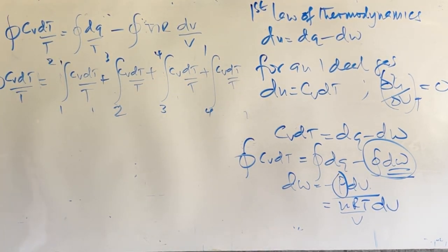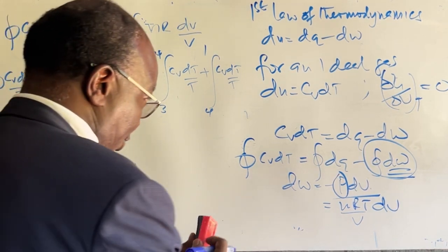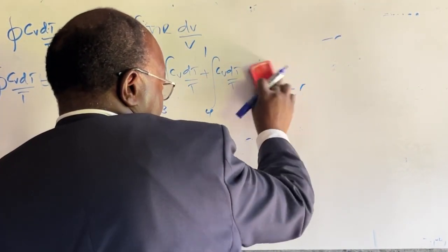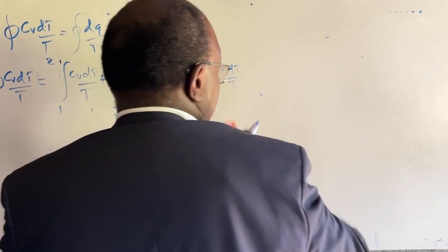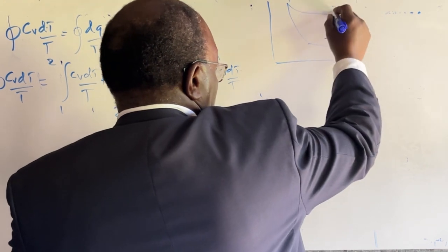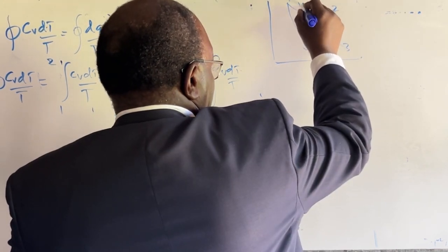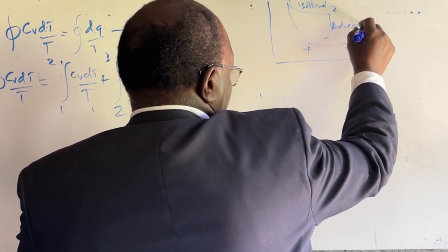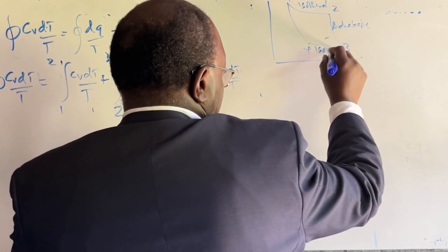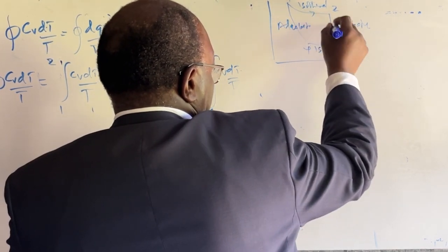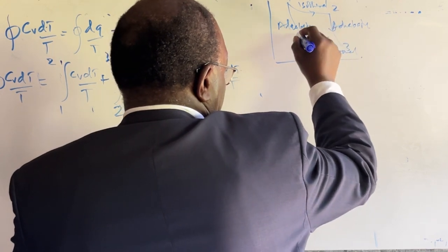Now, if you look at the Carnot cycle, we say that the process was isothermal. Let me just draw it here again so that I don't lose you and so that you can always refer to it. Let me not erase it anymore. That's our Carnot cycle. Remember, 1 to 2 is isothermal expansion, then adiabatic, 3 to 4 is isothermal compression, then adiabatic. Just leave it there, so that you can keep looking at it as you work through that.